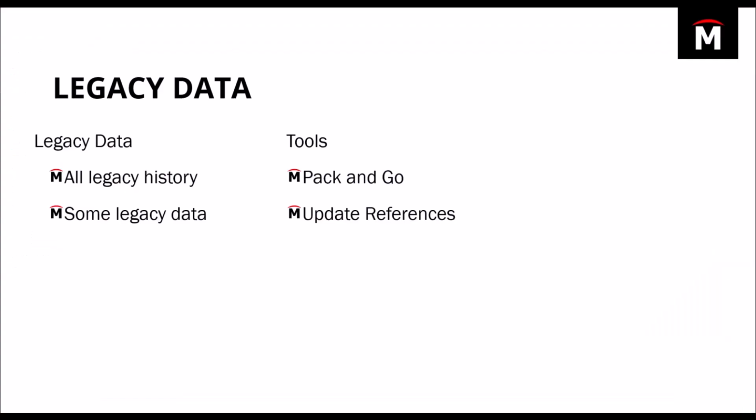As we now have all our shared assets stored in PDM, cached locally, and all our SOLIDWORKS clients are pointing to the right location, we'll turn our attention now to the legacy engineering data. I mentioned earlier that there are some decisions to be made around what data comes into PDM, and hopefully by now you've had a little bit of time to think about that, and you've come to a conclusion on what you want in your PDM system. What I'll do next is go through some examples of moving legacy engineering data into PDM. I'll show you a couple of methods, and a couple of tools that will assist you in this process.